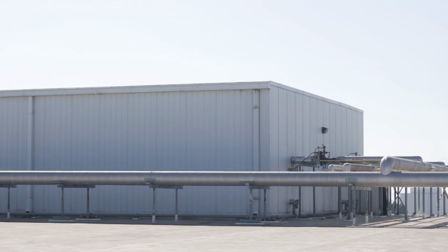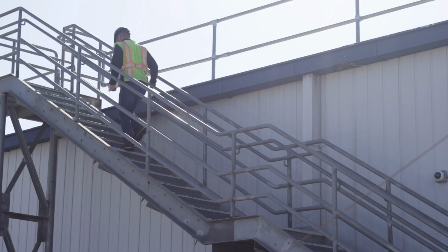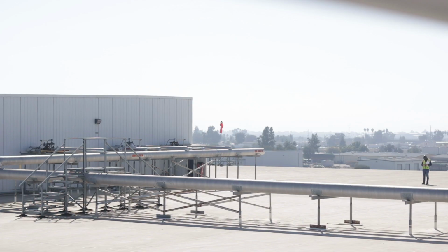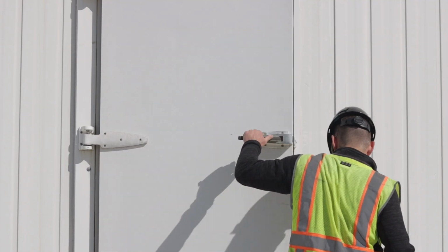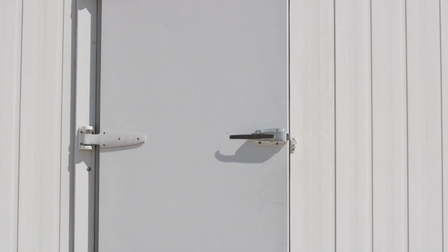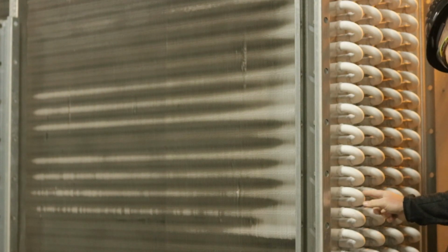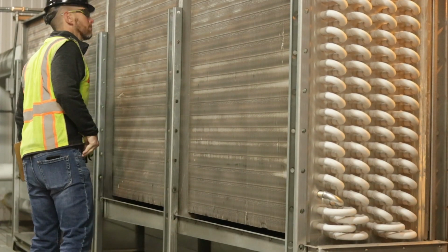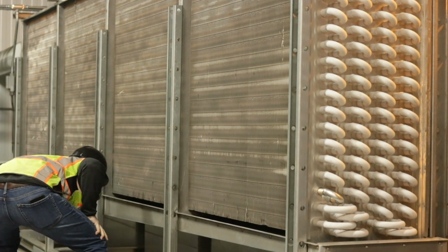Another approach is to install an evaporator inside a small room on the roof. This room is typically called a penthouse and is well insulated so that minimal heat from the exterior enters the penthouse. Penthouse evaporators are easier to access than their ceiling suspended counterparts, and they do not occupy any valuable real estate inside the cold room. The downside of a penthouse evaporator is that they are more expensive than a ceiling suspended equivalent.